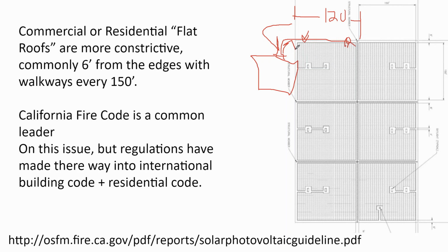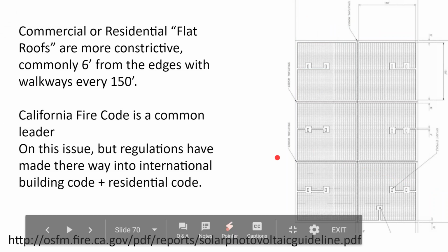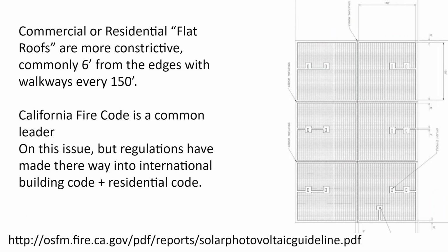the conduit would pull out of the box, leave a rough edge that would bite into the conductor inside it, wearing away at the jacket of the cable and causing a ground fault. And so because these installers were not appreciating the temperature extremes on the rooftop and what it might mean in terms of thermal expansion when you have copper inside of a non-copper, very long conduit run with no expansion fitting, that combined with this fire to burn down the warehouse.